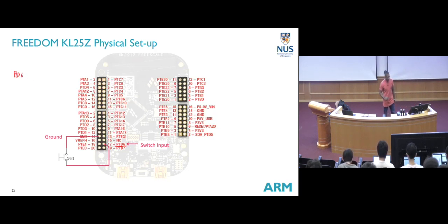If you look at this configuration, what is it? If I draw the circuit here, I have a switch connected to ground. Correct? That is how the circuit is connected. Does this look correct to you? If I press the switch, what happens? It goes to ground, correct? That one is clear. But if I don't press the switch, what voltage will I read? You don't know what you will read, correct?